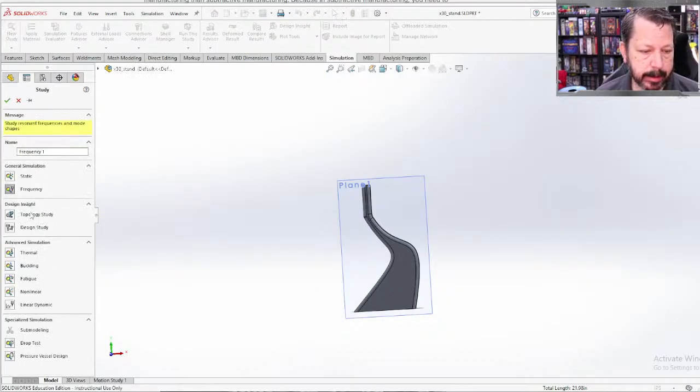And this is where, if you did just the SolidWorks Simulation, not the SolidWorks Simulation Premium, then you would only have this one button. All these other buttons would be here, but they'd be grayed out. You could only do a static simulation, which would just be the one loading configuration, and it's a static load. It'll do the finite element analysis for that one thing, but we want it to continually, iteratively, that's the word, do the topology study, and so we need that part. So topology study is right here.